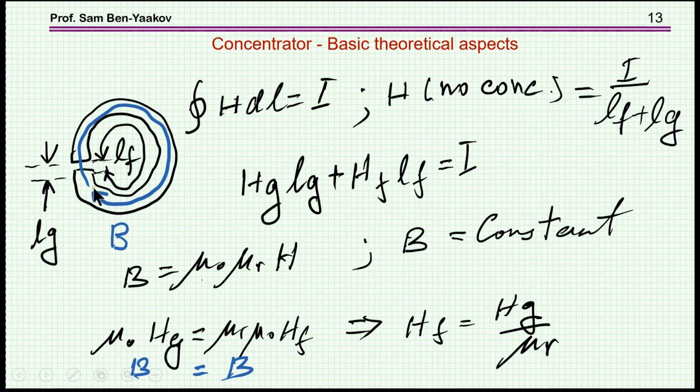That is, we have the same magnetic flux throughout this system, including both the ferromagnetic element and the gap. Save some fringing here, where you might have some of the flux lines coming out. I'm just assuming that the gap is small enough, so you basically have the same flux density within the gap.